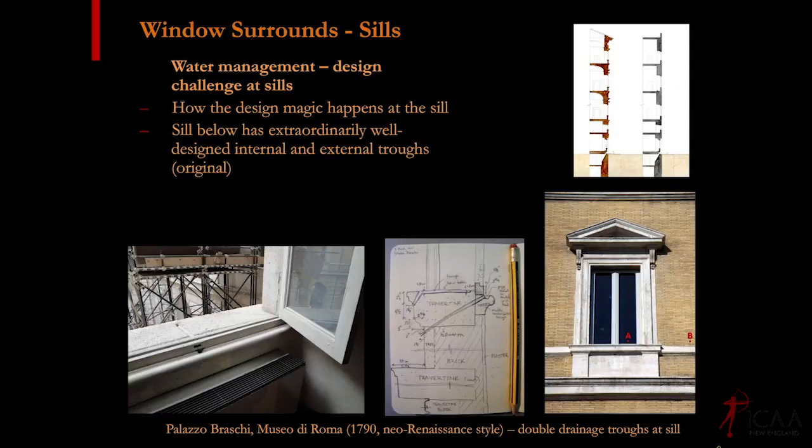You can see it here carved into the travertine. There's a trough here to collect all that water. This all slopes this way. Then there's a weep here that's drilled through to get that water out. And then back inside here, there's another trough, marble, and then there's a pipe drilled through here, a lead pipe, and they've actually soldered the lead pipe to the trough, and there's a little weep here. So you can see there's a dot, those are weep holes.